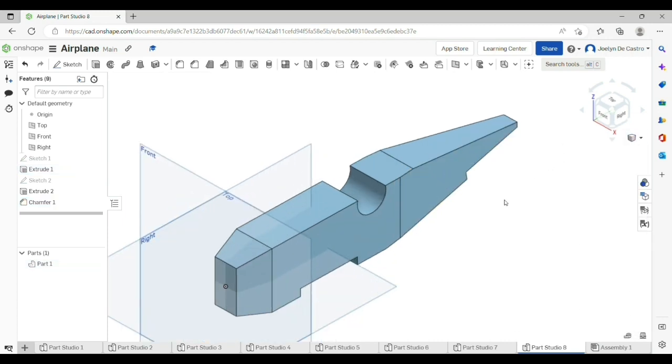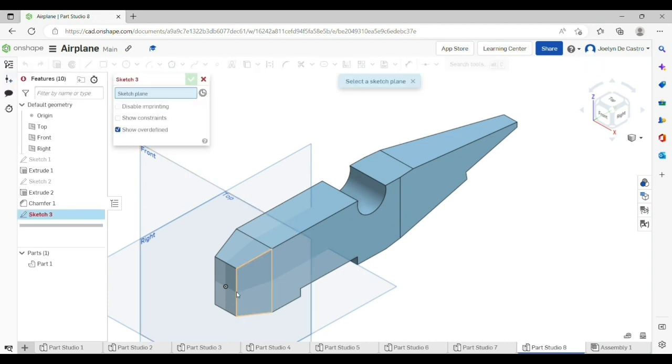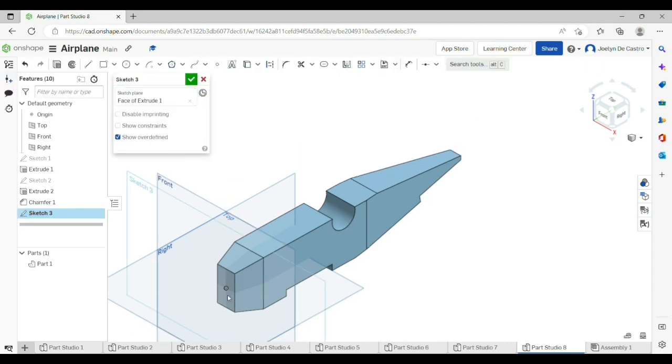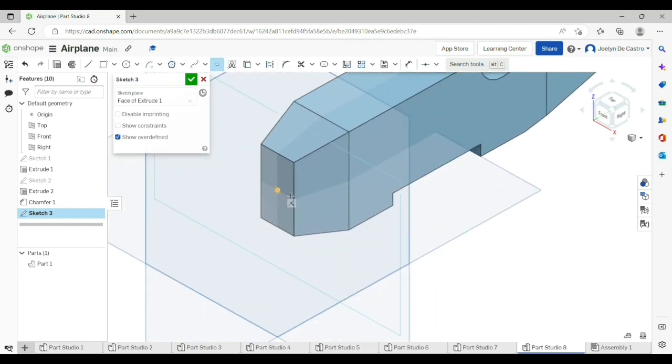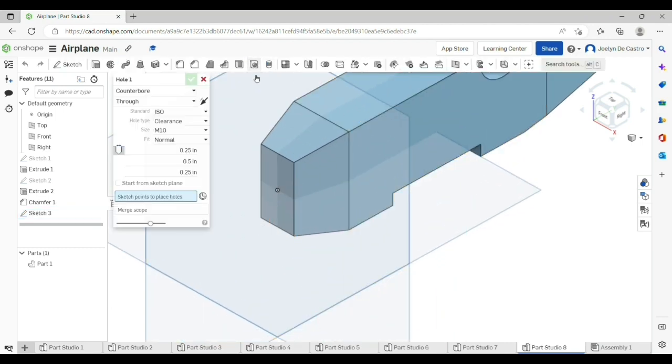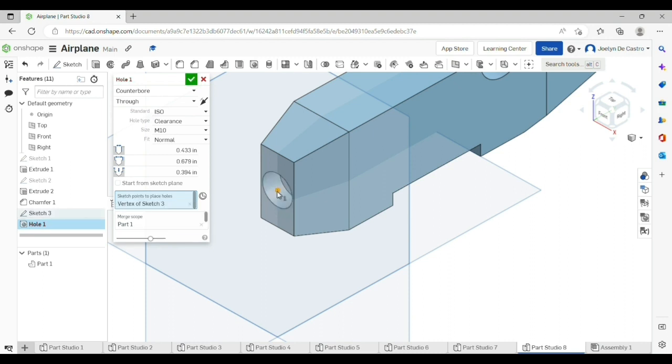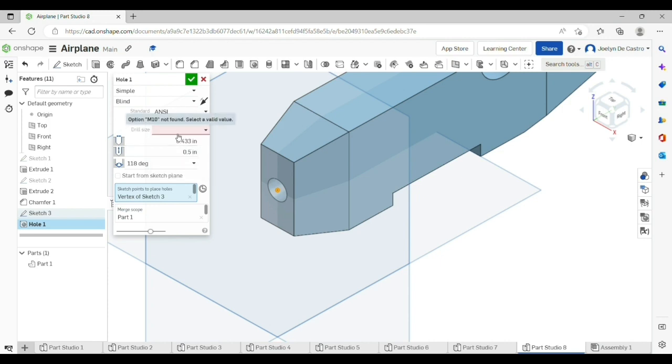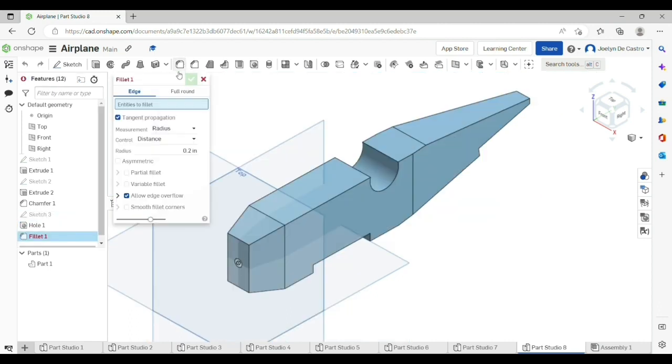There's a 1/4 inch hole in the very front center of the airplane from the propeller. Start the sketch and put it on the front plane and add a point on the origin. Add a hole feature. Click on the point that we added and the setting will be simple. Blind, drilled, and going to be a 1/4 inch and an inch deep.